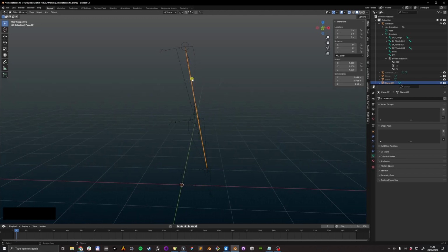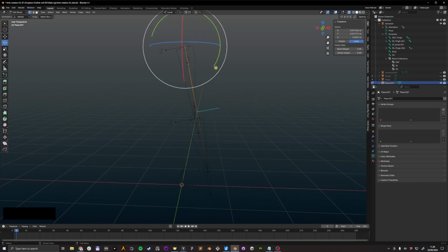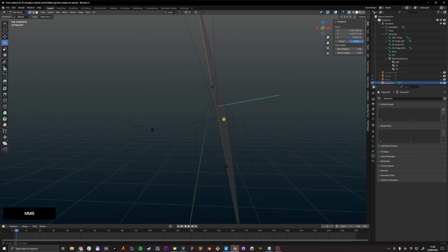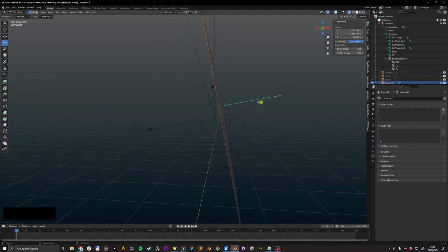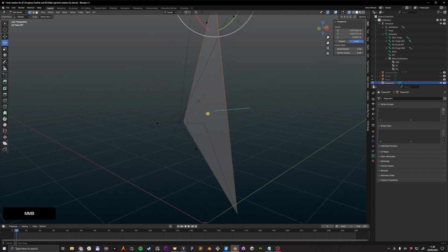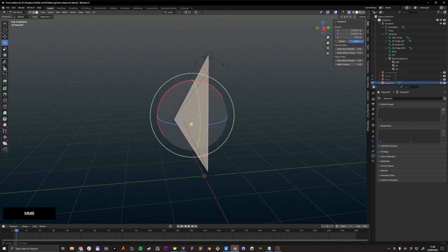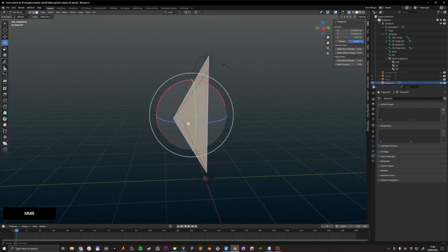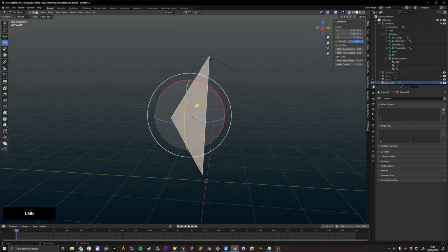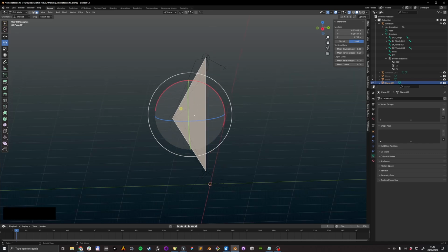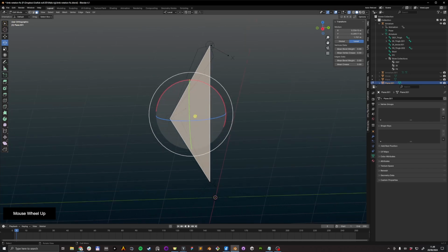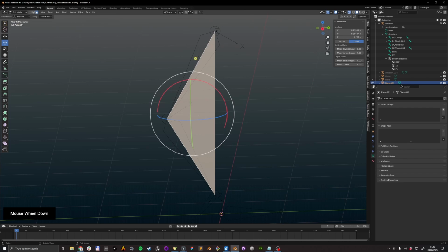So in order for this to work, the blending, the bones all need to sit perfectly aligned with this normal here. Because if they don't, the math is going to be screwing up. So how do you do that then? Well, first off, you need to select this face, then you can go into a custom view orientation. So if you hit Shift 7, that's going to change the viewport so that it's looking directly down the normal of this face now.